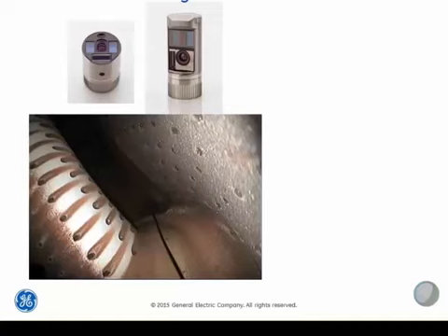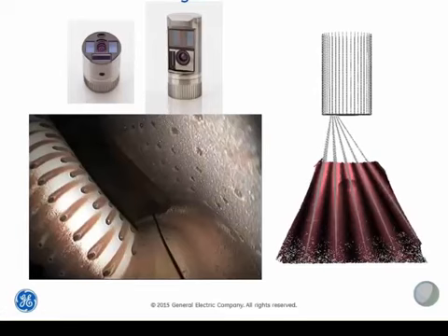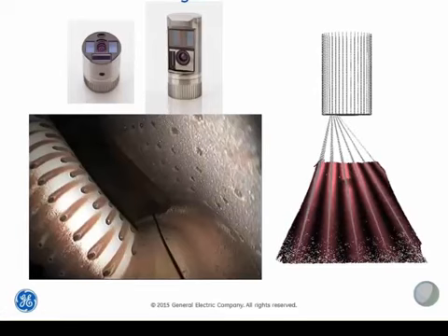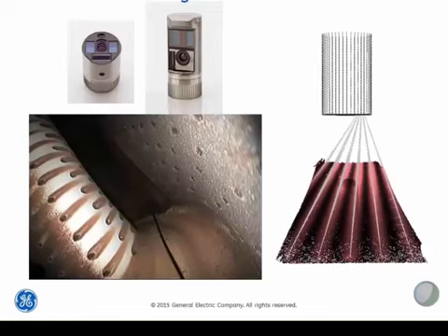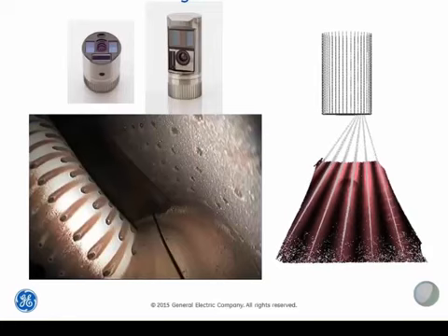So our second and more advanced 3D technology is called 3D phase measurement, or sometimes 3D PM. So here we have 6.1mm diameter detachable tips that include a patented structured light projection system. So we capture images of a sequence of line patterns projected out from these tips, and then we process those images using a technique called phase shift analysis, which allows us to, again, compute a full 3D point cloud of that viewed surface.